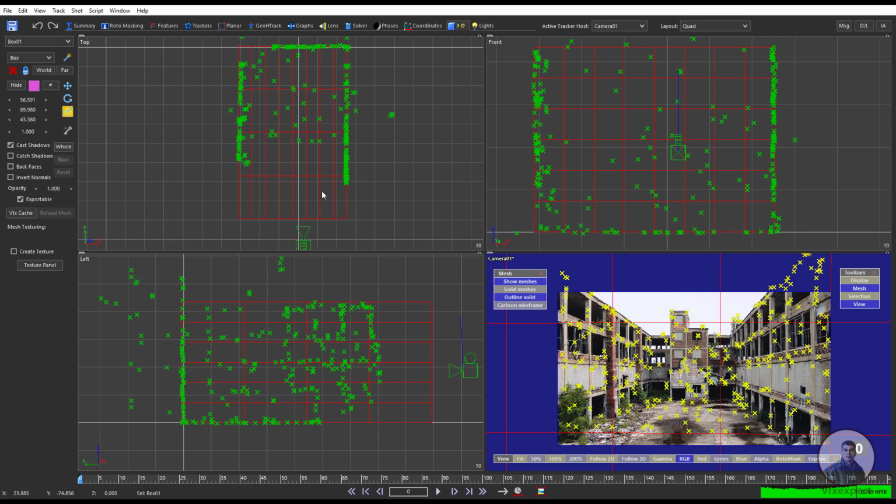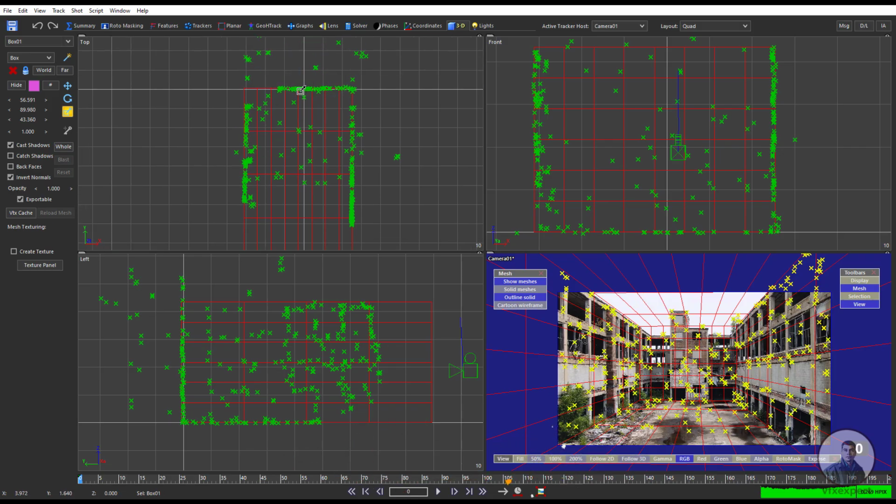So now after this, we have to select this geometry. Then on the left side, bottom side, you will get this invert normals option here. So we simply click on invert normals. Now if you look, I am getting this, just like a room here. Remember this geometry, I have created it till here. We have to focus on these points here. But if you want, you can also create till here. This totally depends on you, but this is only for explanation here.